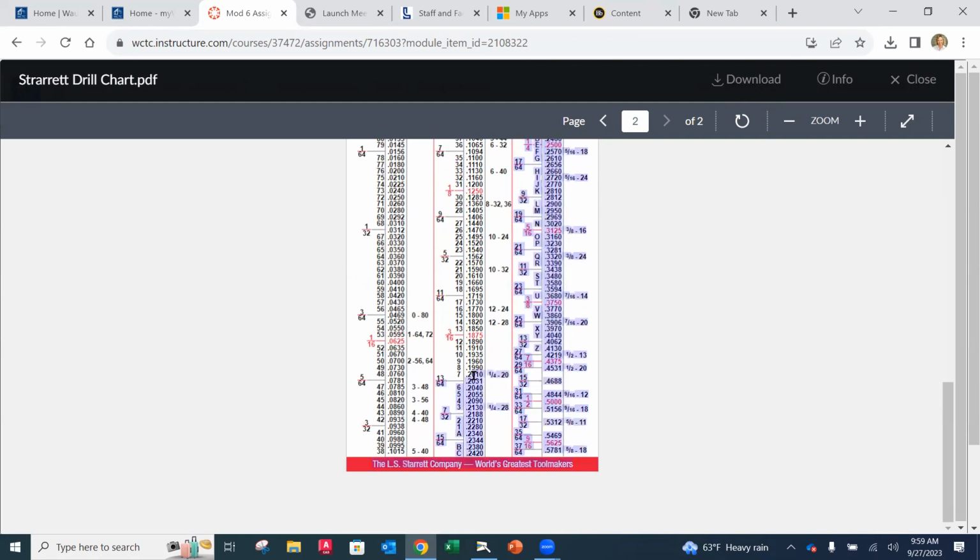So number 7 drill corresponds to 0.201. Now remember, my outside for a quarter inch is 0.25. So I'm going to drill first with 0.201. I'm going to get all that material out, and then the tap is going to create the major diameter and the spiral in there so that it's going to then fit with a quarter inch. So again, a tap can't take it all out in one operation. I have to drill first, number 7 in this case, and then I'm going to create my threads after that.